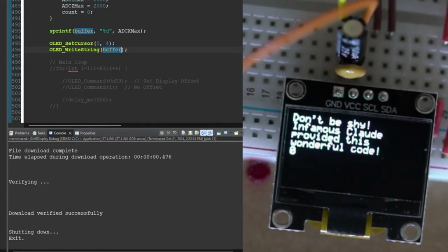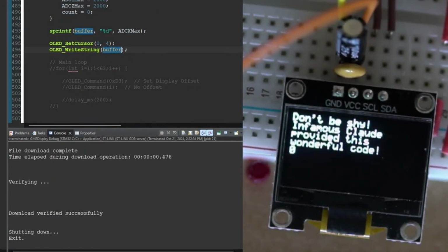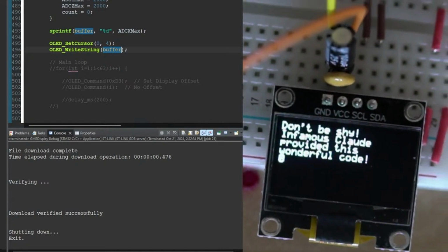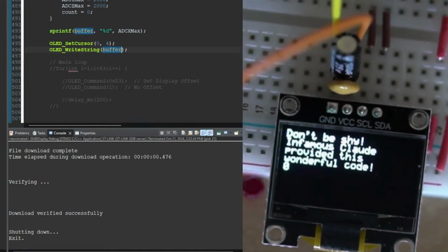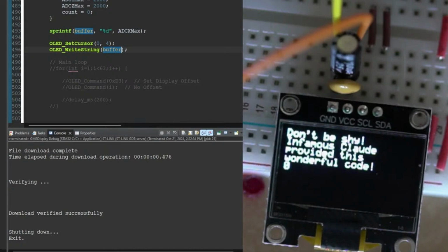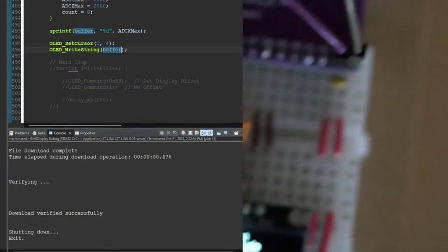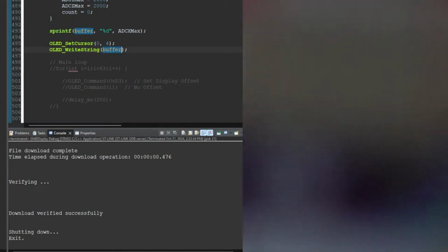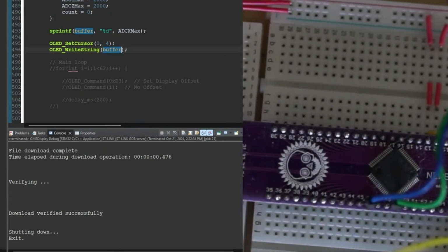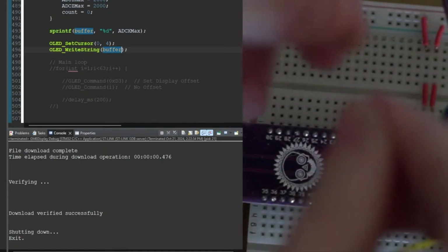Okay. All right, let's put a wire in there. We could wire it up to 2+ volts to the power rail and see what number we get. I would want to do that with a resistor though. Let me get a resistor somewhere. I don't like to pull pins high completely, like just with a straight wire, only because I don't know what would happen and I don't like to short anything. All right, so I'm going to put a resistor while it's on, so I should get a higher value. I'm going to use a 330 ohm resistor.